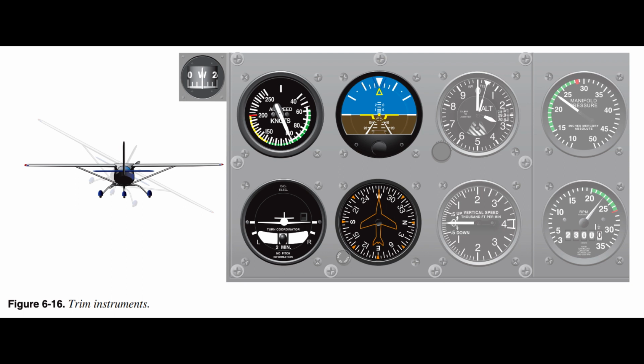Example of primary and support instruments. Straight and level flight at a constant airspeed means that an exact altitude is to be maintained with zero bank, constant heading. The primary pitch, bank, and power instruments used to maintain this flight condition are: 1. Altimeter supplies the most pertinent altitude information and is primary for pitch. 2. Heading indicator supplies the most pertinent bank or heading information and is primary for bank.